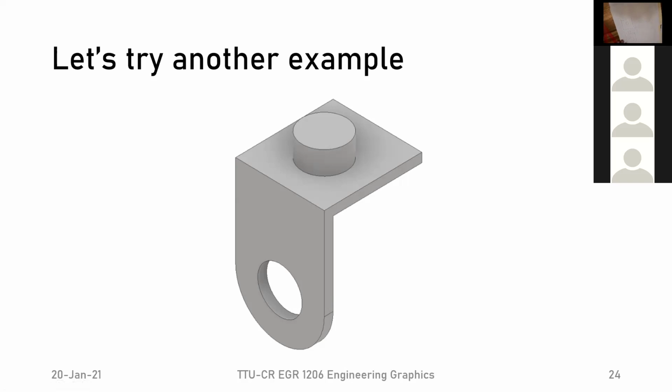Now, before we continue with the right side view, let's get rid of the center because there's nothing there, so we shouldn't have a point there. Before we get to the right side view, we have to add a couple hidden lines. Of course, if we could see this line coming from this direction, we can also see this line looking down from the top. So it's the same kind of edge that we see. So let's do another hidden line right there.